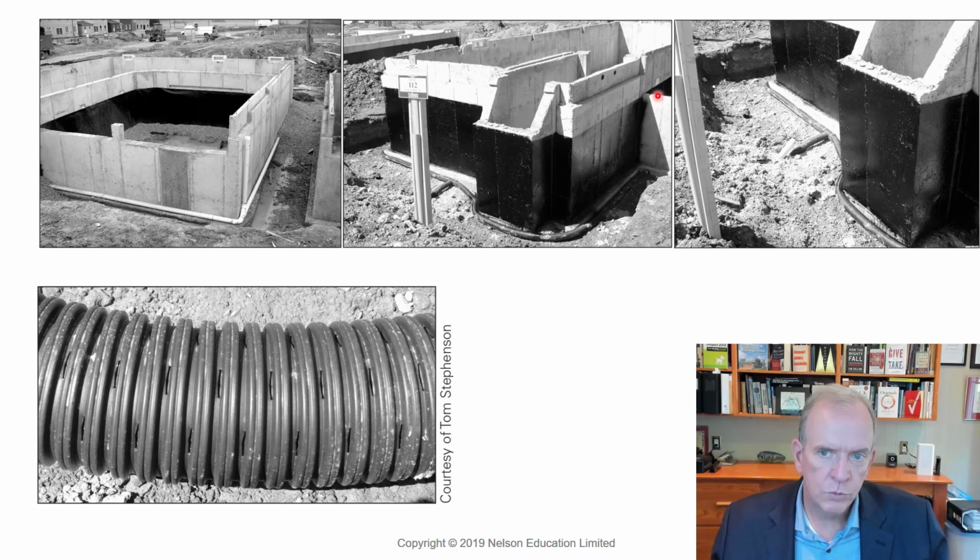of the house. And you notice where the garage is, they don't place it, but inside the garage they do, because they don't want any moisture that might be getting into the ground from underneath this garage slab to leak through to the basement. So that's where the actual damp proofing goes between these points.